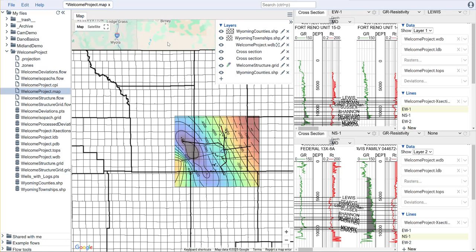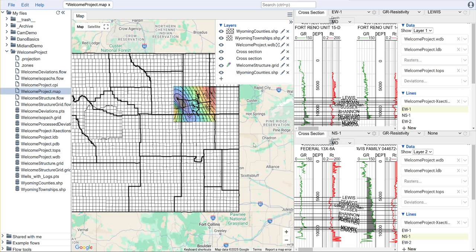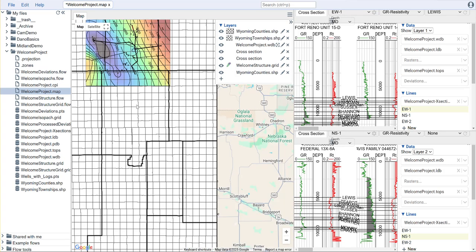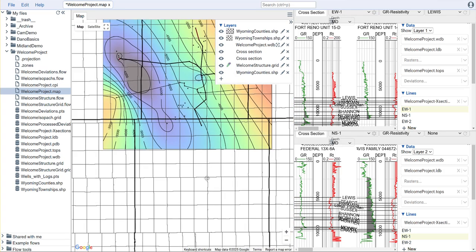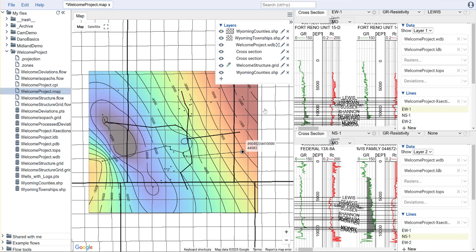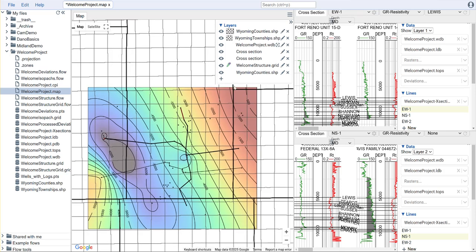And now we have this extra shapefile here on the bottom that we are using to make a white background. And if we zoom out far enough outside the state, we can see that the Google map is still back there. So, we're just hiding it away, so to say. And if you need to do this for a bigger area, you can, of course, load up a map of the US or Canada or wherever your area of interest is and color that white and put it in the background.